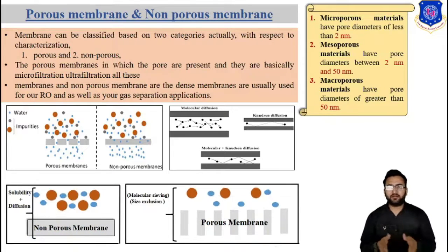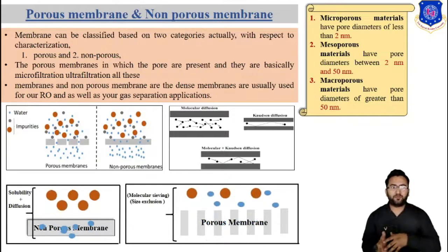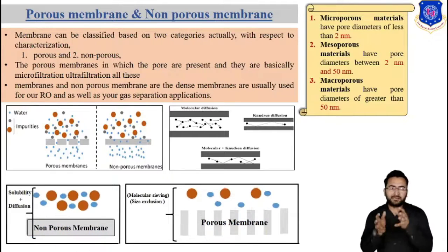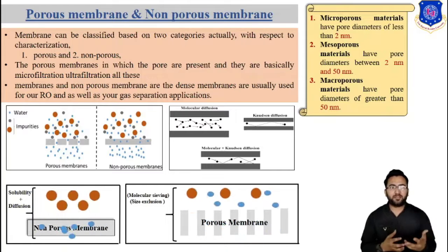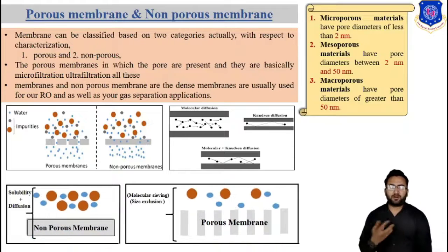So that is under the structure related parameter. We basically determine pore size distribution, top layer thickness and surface porosity. In the case of permeation related parameters, we actually determine the separation parameter using some real solutes that are more or less retained by the membrane surface. This is called cutoff measurement or cutoff experiment.